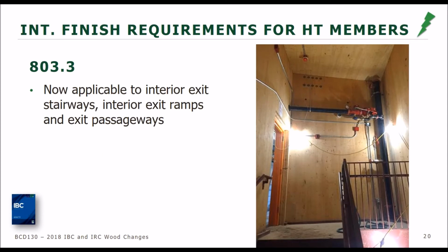AWC was the proponent of this code change. That was FS132-15. For quite some time, the regional managers, the folks that are providing assistance with, or actually providing some thoughts, kind of linked to the code officials for AWC, we felt that it was not appropriate, and we had felt this way for quite some time. We felt that it was not appropriate for heavy timber elements to be exempt from the interior finish requirements of the exit enclosures. It's just that exception has been in the code for a long time. But again, we just felt it wasn't appropriate.